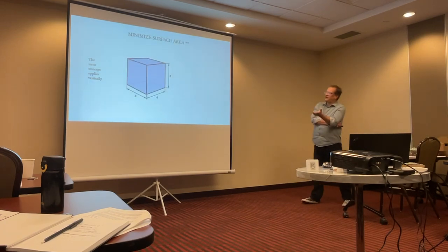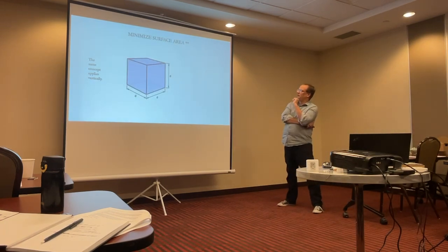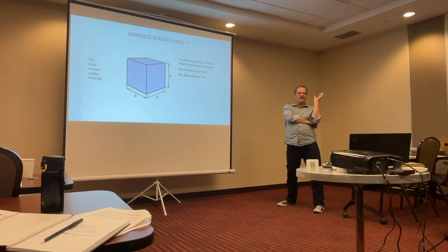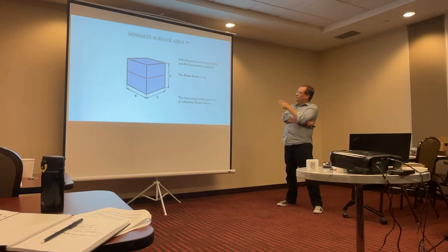So this is an example I've used for years. If you have a better one, please do, but I kind of use a cube. It's got 6 areas of surface and 1 area of floor, so it's 6-to-1. Could never certify as Passivhaus even if you put on gobs of insulation. As soon as you make it a 2-story cube, it's 3-to-1. It's a really efficient house. This is what we're aiming for in a lot of single family and other projects, just that addition of the extra floor.